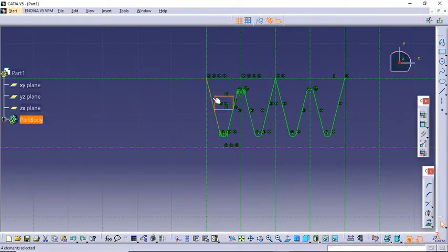Let me remove this belt, it is really not desirable. Okay, now again smoothen out all these things. So what I was saying is that all these dimensions are important. Right now I am not paying too much attention to these dimensions, but they are important: 1, 2, 3, 4 and one more. Now let's again take the mirror image, click here, here it goes. Now smoothen out this one with the same dimension of 1 mm radii.